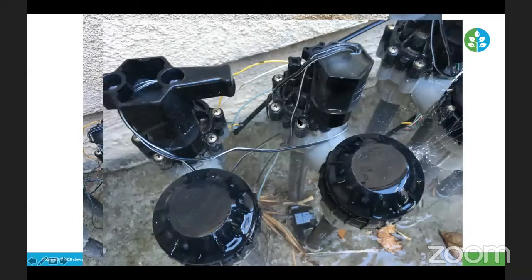Either you have a shutoff valve that will shut off the irrigation or isolate the irrigation, I should say, from your residence. Or you would have to call the water utility to shut the water meter off, because if you did undo this or take the solenoid off when the water is still live in your system, you will be soaked very, very quickly. And it will not be a pretty sight.